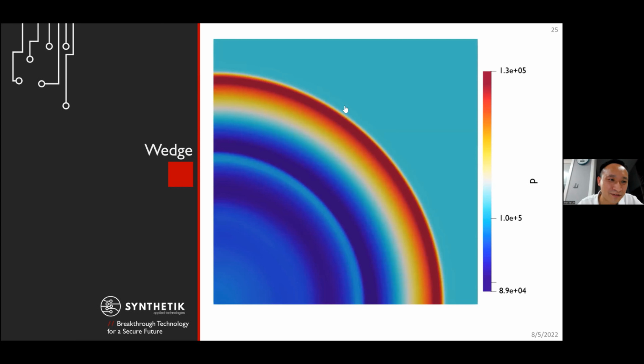Okay, the next question is from Jason and Professor Heylmun. Thanks for your great talk. My question is, can BlastFoam deal with the situation where mixtures contain more than two materials in the same grid, such as reactant, product and the air existing in the same grid at the same time? I think this is for the volume fraction alpha. If it can, how do multiple materials mix in BlastFoam?